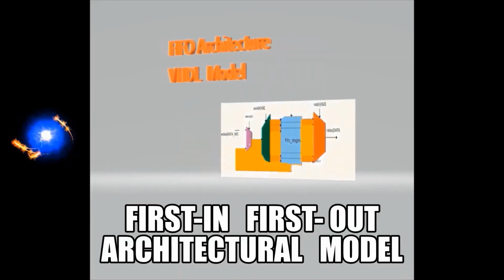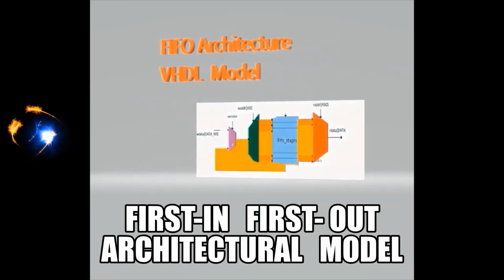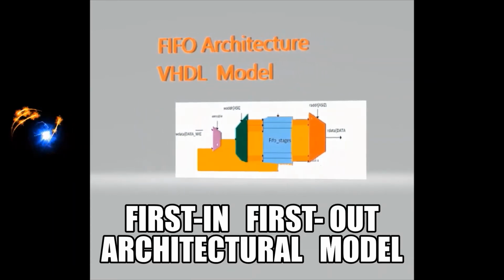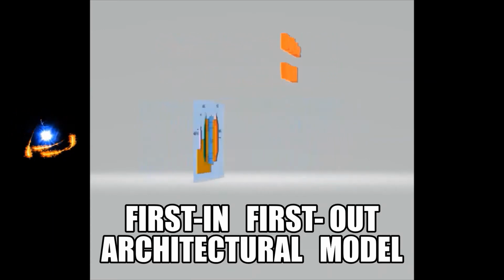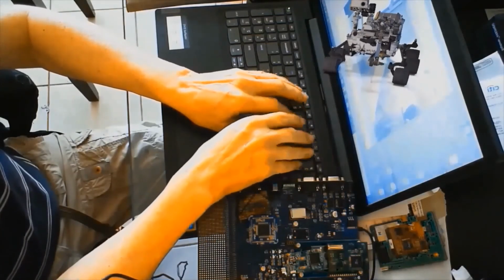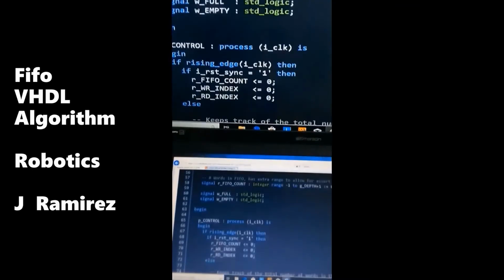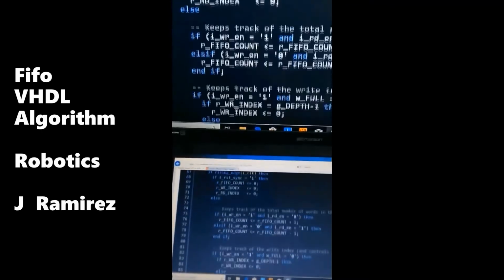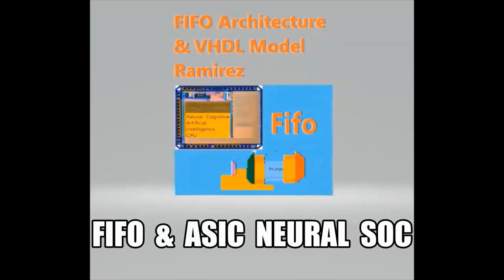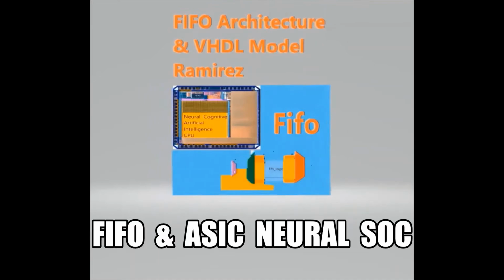In order to write data into the FIFO, first in, first out, first push the data onto the data in bus and then strobe the write enable input high for one clock cycle. It will write whatever is on the data in bus into the FIFO's internal memory. Writing in bulk, the write enable signal is left high while changing the data on the data in bus each clock cycle.